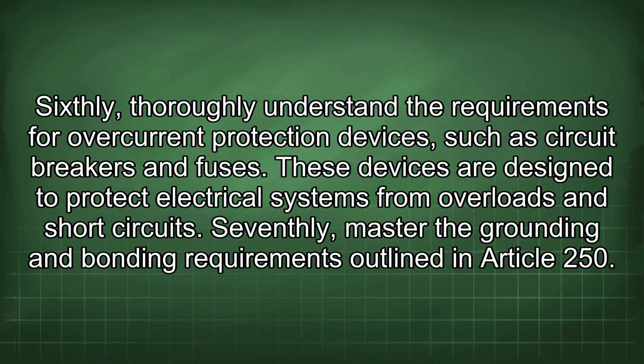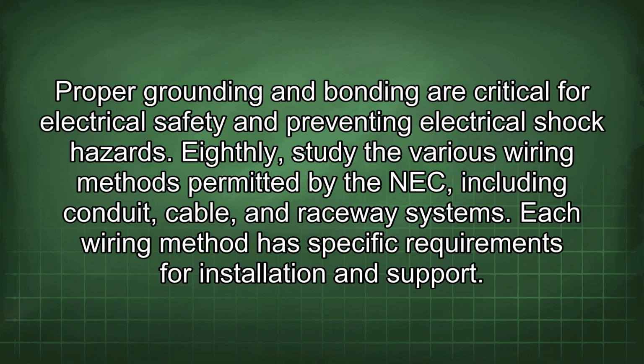Seventhly, master the grounding and bonding requirements outlined in Article 250. Proper grounding and bonding are critical for electrical safety and preventing electrical shock hazards. Eighthly, study the various wiring methods permitted by the NEC, including conduit, cable, and raceway systems. Each wiring method has specific requirements for installation and support.